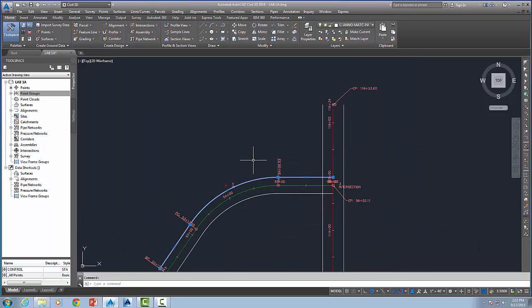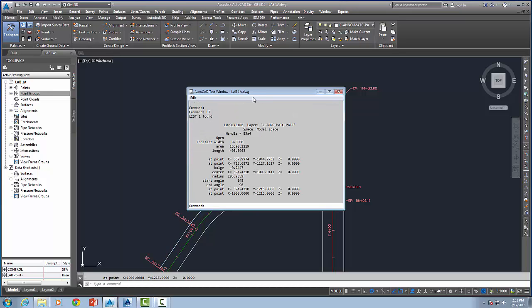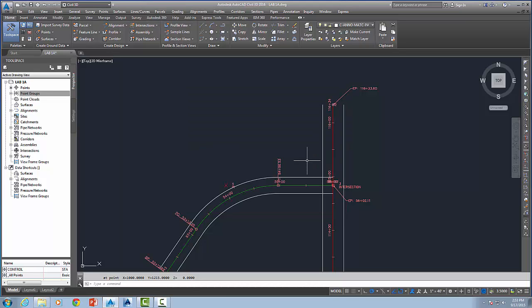If you click on those and list them, you will see what they actually are: polylines. They're lightweight polylines. And they have been put on a certain layer. They go on whatever I think the current layer was. So it could be cognizant of what you're setting layers up to, or move it later. If you didn't want it to be a polyline, you can explode it. If you're okay with it being a polyline, you can just leave it as a polyline.